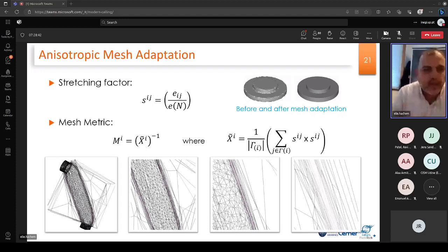By doing this type of coupling between the level set and the mesh, you can have a very smooth interface. So when you print it, you don't need to spend your time fixing small defects everywhere on the surface. So these are the two reasons. The first reason is that you can minimize the computational cost and increase the accuracy of your method at the interface. The second one is related to fabricating the piece itself without having any defect on the surface. So this has some defect. This has no defect. You can see if you print this part, you're going to see the defect.